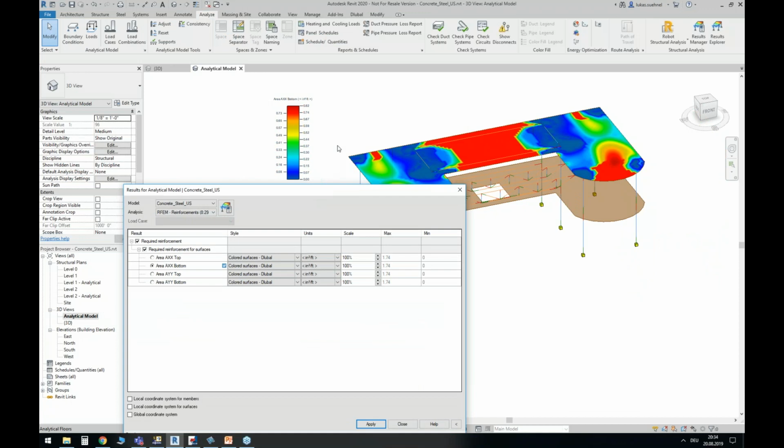So the Revit interface allows us to export the content of our Revit structure to RFEM or RSTAB. We can design it there if it's set up correctly and nicely in Revit. We can make a few changes in our RFEM and update the Revit model based on the changes we made in RFEM. And we can also import results. So we have the full circle based on the first workflow that I showed you in the beginning of that webinar.